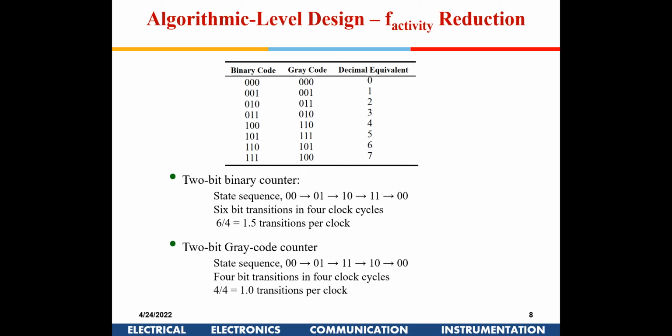So those kind of timing circuits and counters are there, which you can run in a binary code also. Now can I put gray code into that counter? Why not? If I put gray code, all that I have to see is when the count is becoming 0. In a binary counter, I will initially put 111 and keep decreasing the count, and after these many counts it will come to 0. For a gray counter, I will put 100 initially, and this will also take 7 clock cycles to come to 0, right? So it will take the same time. But what is the advantage in having a gray code out here?